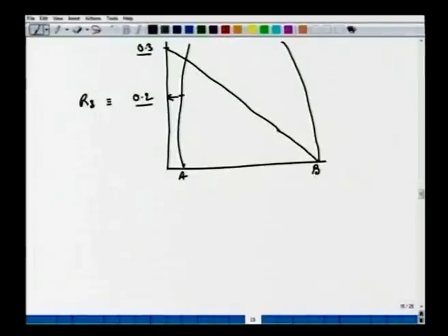The amount of solvent is not known to us, so to find out how much solvent we require, this is 1 fresh solvent, so that the treated stream, this raffinate, contains 0.2. So again we have this R stage, in equilibrium with the extract phase from that stage. So again here we have to do this exercise. We find the tie line which connects this raffinate concentration at 0.2.